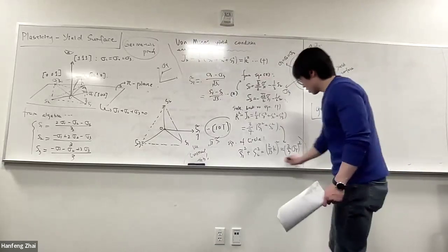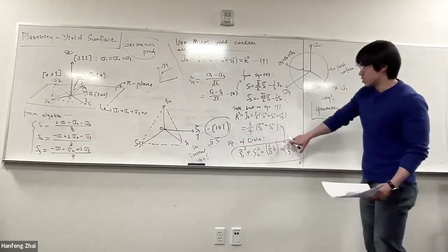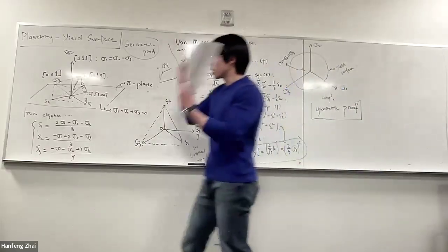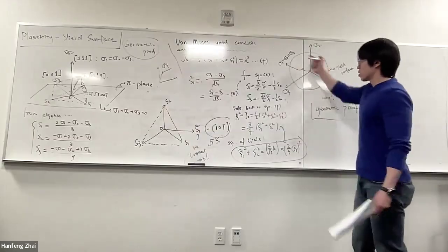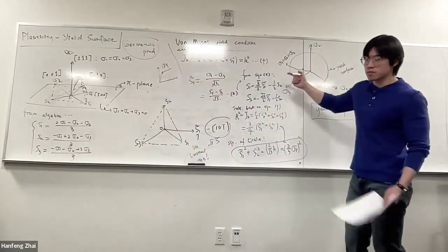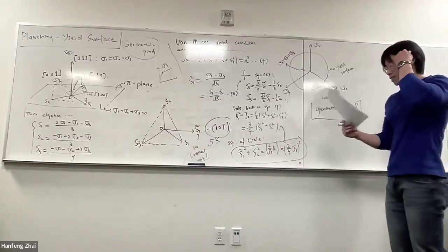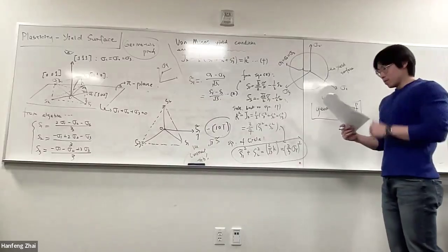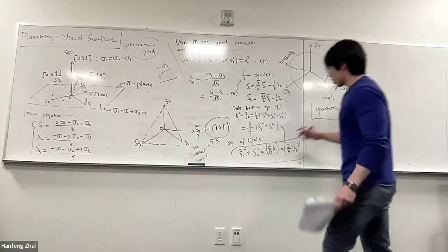So this is literally the equation of a circle, that using pure geometric concept, we kind of prove that the von Mises stress yield surface is a circle, right? Okay, so I hope now this clarifies your understanding. And one more comment.